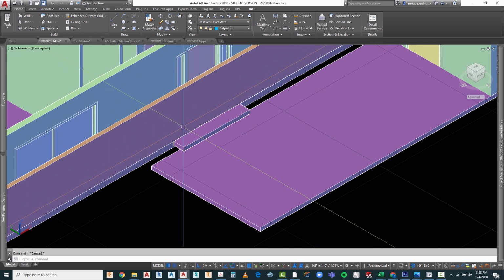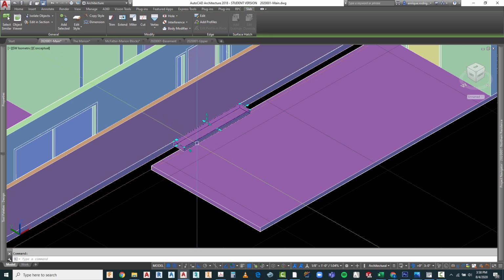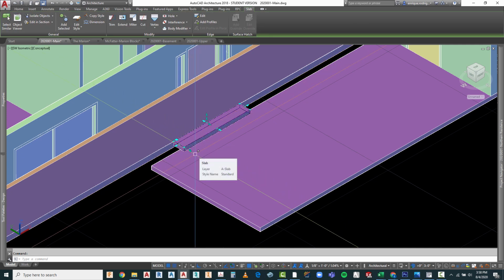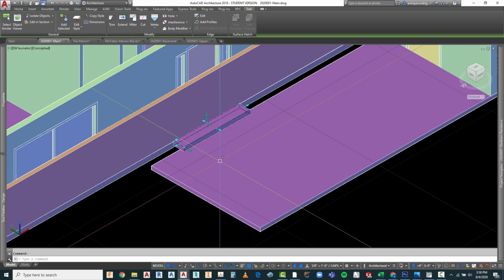What we're going to do is we're going to go ahead and take a 6-inch step and then another 6 inches to that. So what do we need to do? We need to make 2 adjustments to this. We need to adjust the top of it to -6, and we have to adjust the depth to 6. So the bottom of it's going to rest at this point, going to go up 6 inches, and then it'll be another 6-inch step to the main house.